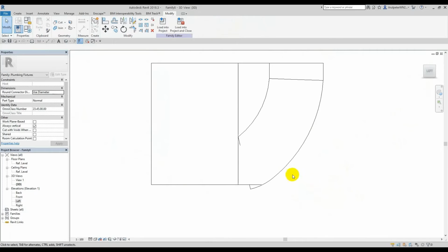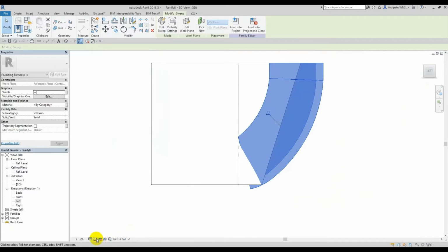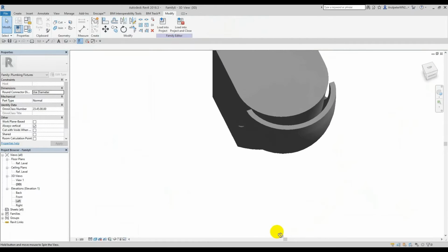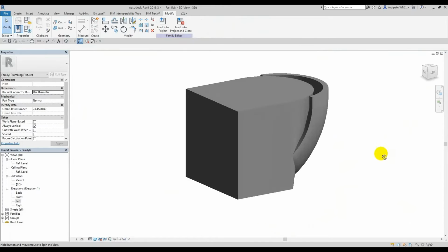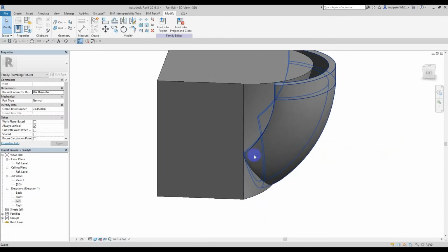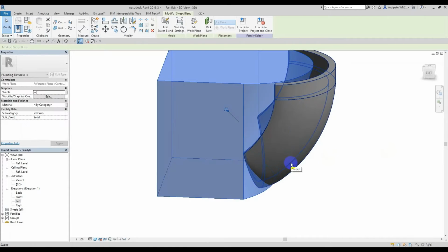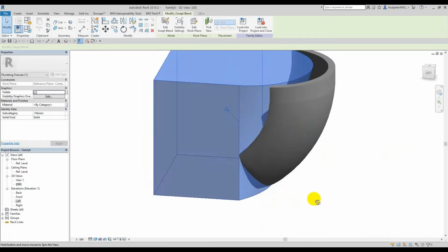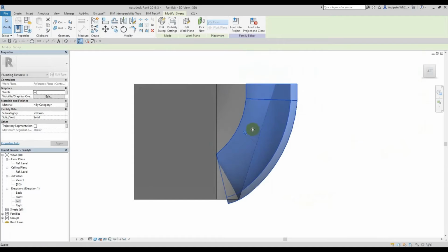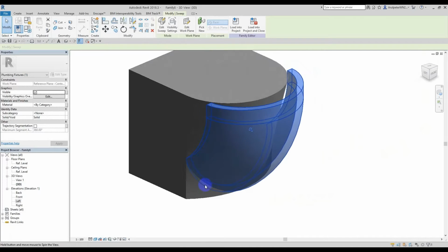To the left view. So right now, shaded. Okay. My profile becomes like that. Actually, I don't want to see it like this. I need to cover my street more than this. So now it's time to change the Revit street profile, like this.